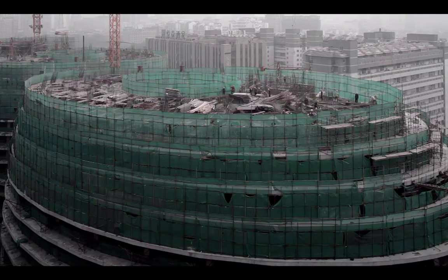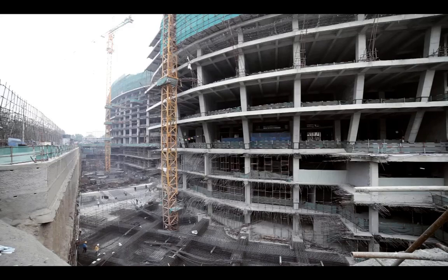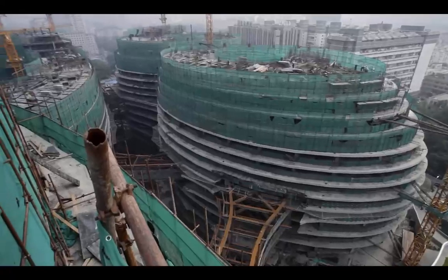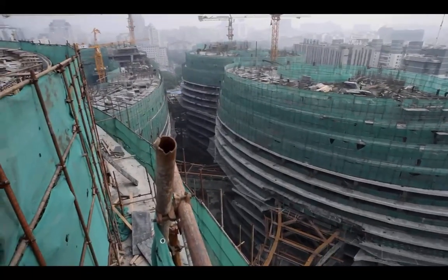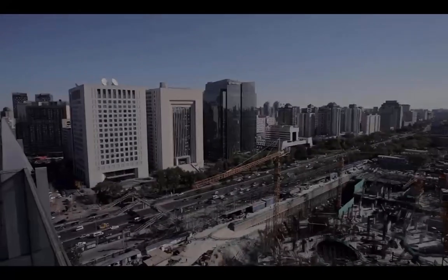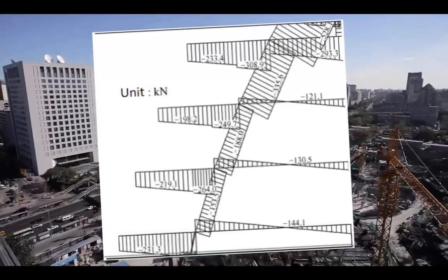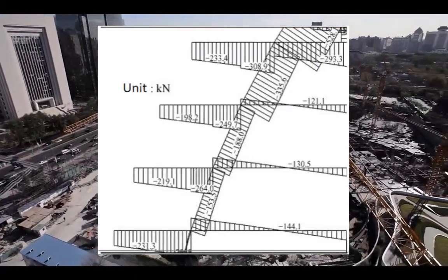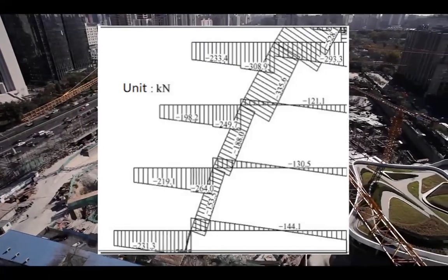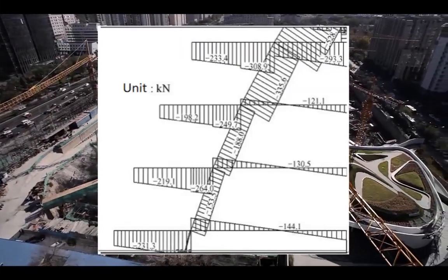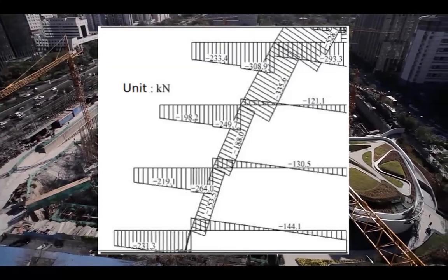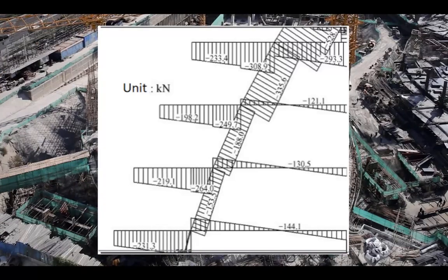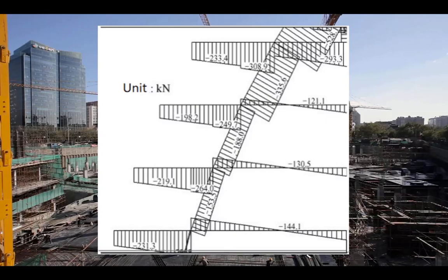It is basically consistent with the outer contours, which makes the layout of the building simple and the structure transmission clear. In terms of structure, because the actual pressure line of the inclined column coincides with this axis, the vertical force along the length of the inclined column will not only bear the axial pressure, but also shear force.